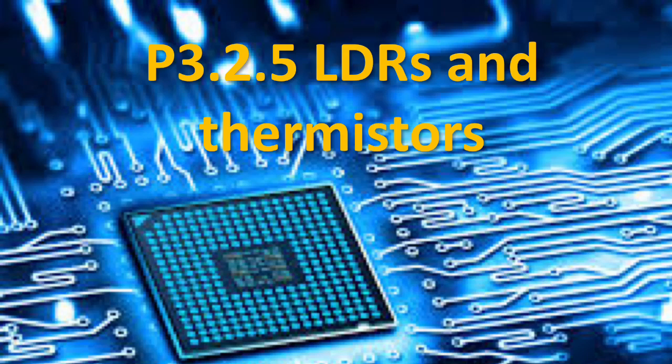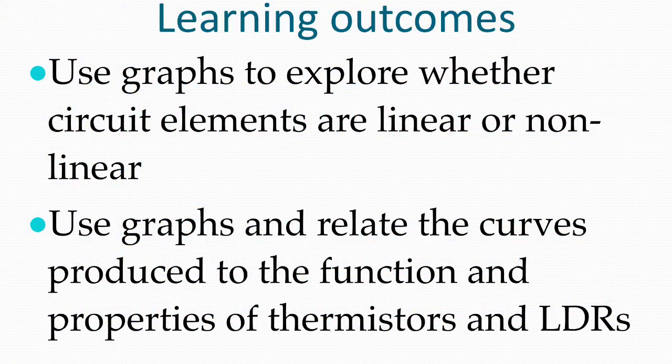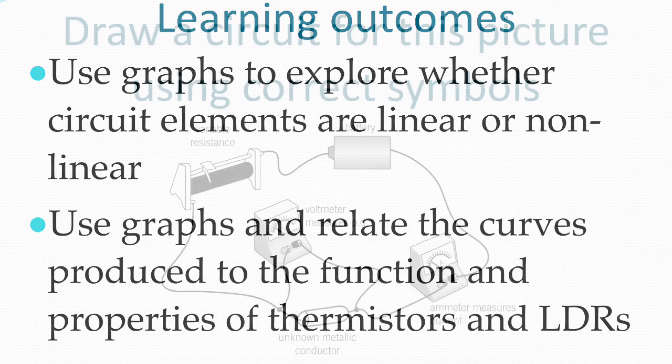Hello and welcome to today's lesson on light-dependent resistors and thermistors. Our two learning objectives are to use graphs to explore whether circuit elements are linear or non-linear, and relate the curves produced to the function and properties of thermistors and LDRs.